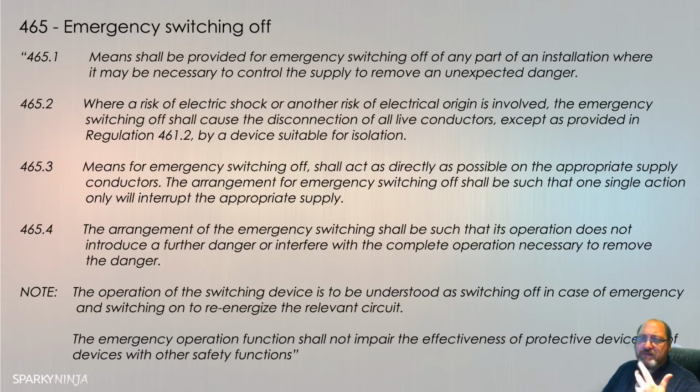So technically, if we were to disregard what we've already talked about in part 3 with division of installation and things like that and accessibility, technically we could install a fuse board in the home and just have all of the circuit breakers as the switches. You know, we can install light circuits and say, oh, go there, there's your switch. That technically is compliant with that switching arrangement in the regulations. Obviously, assuming that we haven't considered division of installation. So that's just an example there.